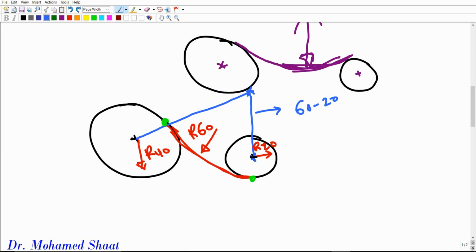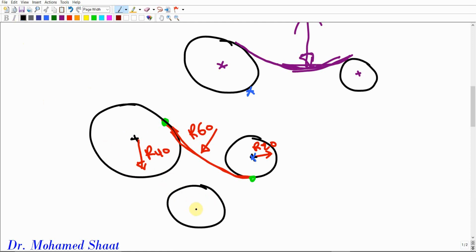So how can we figure it out directly? You're just going to ask yourself very simple questions. I'm going to give you another approach to identify the values of the radii. Is it going to be the sum or the difference that you use for drawing the curves to locate the center point? Just a simple question. First of all, the question we discussed before: where should the center point be located? It should be located somewhere above here. Then, if I ask you to move from the center to the center of the circles this curve is tangent to, right? What if we have a third circle here and it has a center?